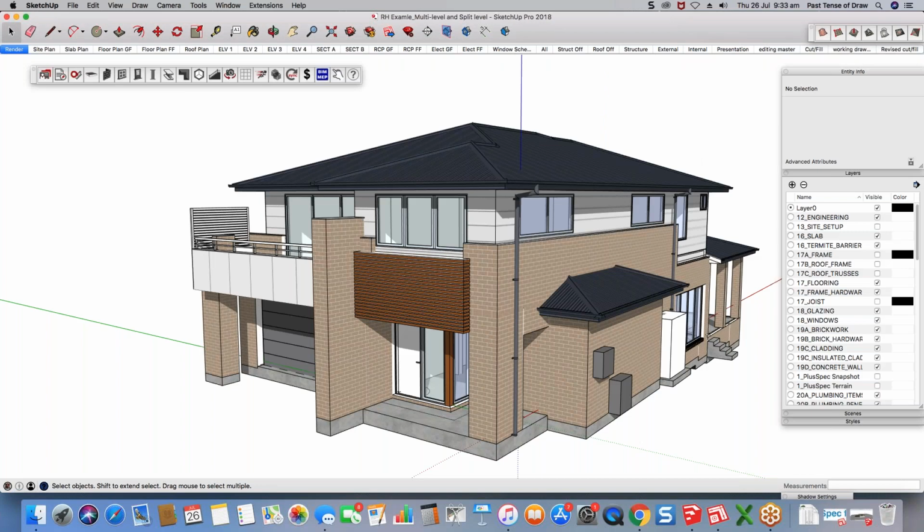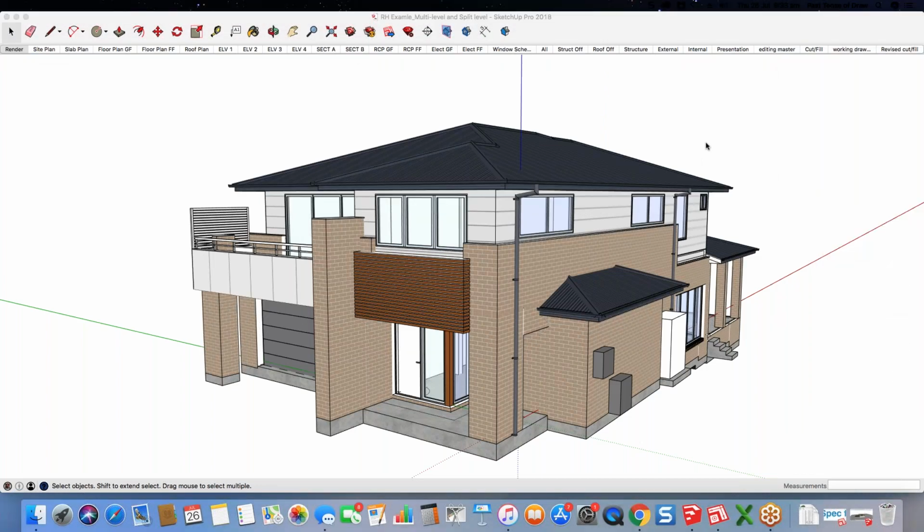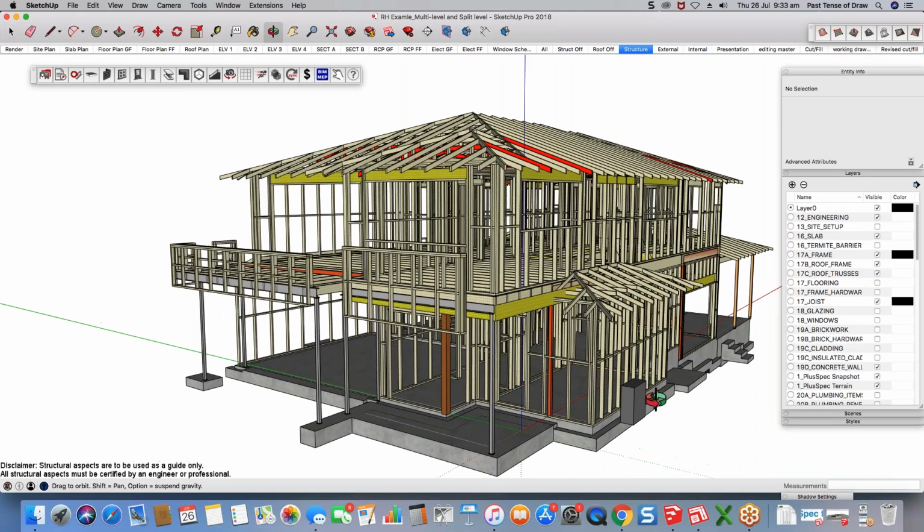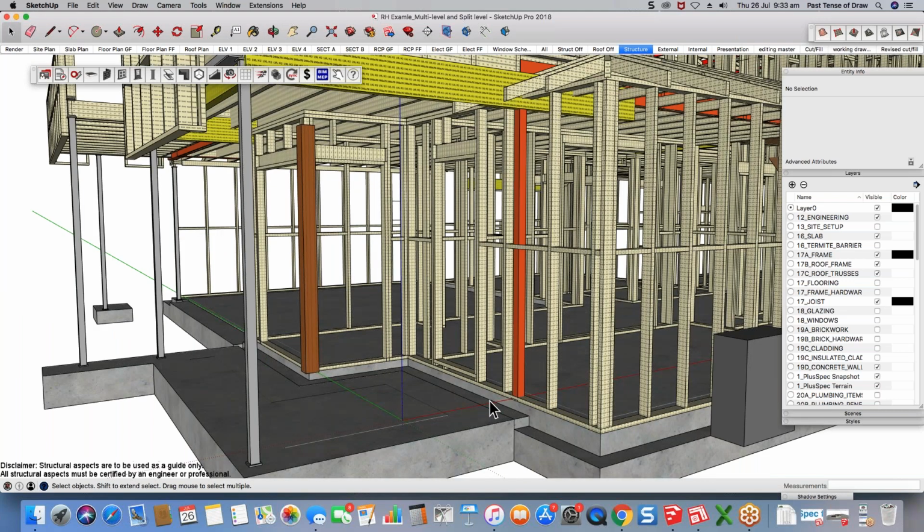We'll also show this one here. I'm just going to quickly talk about this one as well. So again, whilst we're in this one, if we were to go into the structure here, you can see that you're capturing so much here. But it's very easy for you to determine the different heights. And you can see if you've got different parts of your slab or whatever that are at a different height, then you're just modeling each part independently, and then you can change the footing detail or the information to suit what you want. You can also do step downs within the slab, etc.